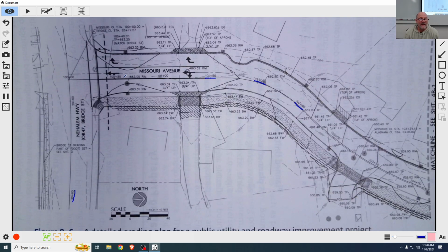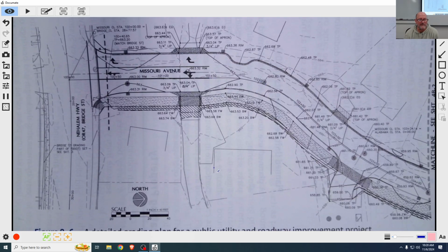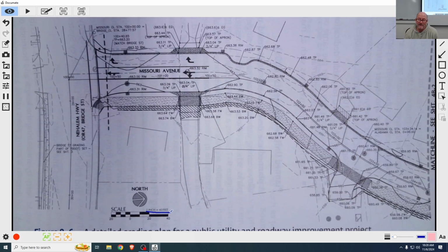Okay. What else are we... Anything to point out that's in here? Besides the north arrow and the scale, I'm seeing two types of scales, right? So I see this 1 inch is 40 feet. And we have a graphic scale. And probably, I would expect somewhere you would have 1 to what, 480? Which would be its absolute scale. But maybe not.